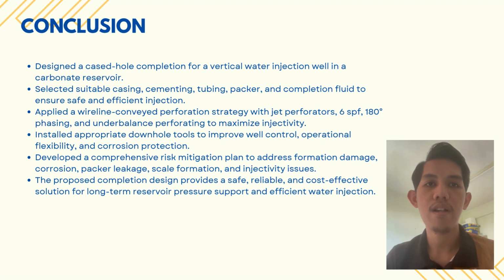In conclusion, our proposed completion design is suitable for a vertical water injector well in a carbonate reservoir. We selected a cased-hole completion to provide better zonal isolation, maintain well integrity, and allow future well intervention. The casing, cementing program, tubing, packer, and completion fluid were carefully selected to ensure safe and efficient water injection while minimizing corrosion and formation damage.